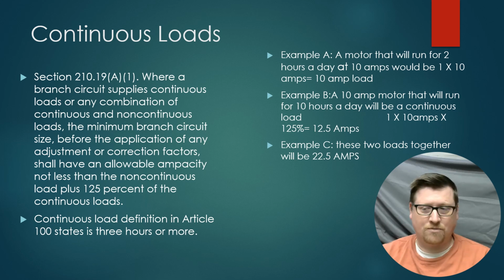We're not having to pad those numbers. But if we have a device that, as it's running constantly, builds up heat in that wire from that electricity, that amperage running through that wire, and we don't give that wire a chance to dissipate that heat, then we're going to pad the amperage that we're using for choosing the wire size.